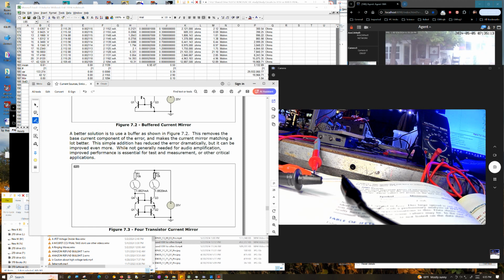Because again, if you use high voltage transistors in here, there's no reason this thing couldn't operate at 100 volts or more. Again, keep in mind your current and safe operating area on your transistors. If you're dissipating more than 1 or 2 milliamps over a large voltage, you've got to take the power handling capabilities into account, of course. But the point is, you could do it, and make a current sink or source, because I think these things can work in reverse. I think you can make them source mirrors as well as sink mirrors, like this is a current sink. I'm pretty sure I've seen them that way.